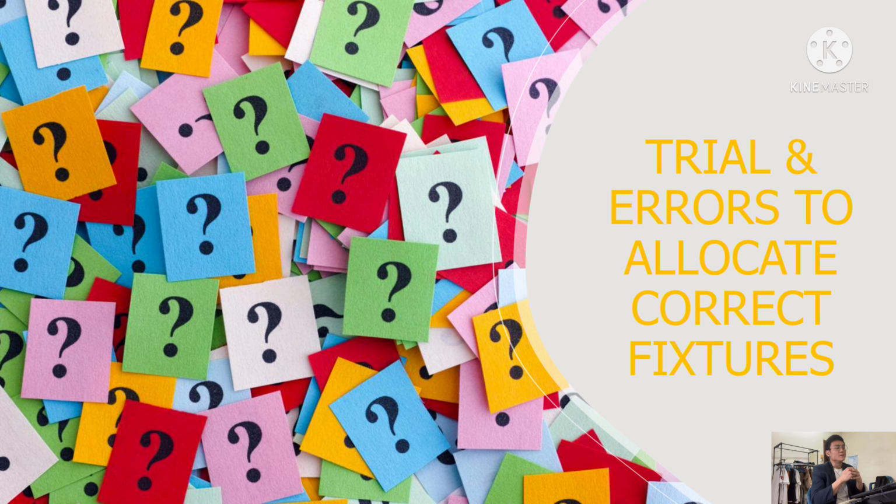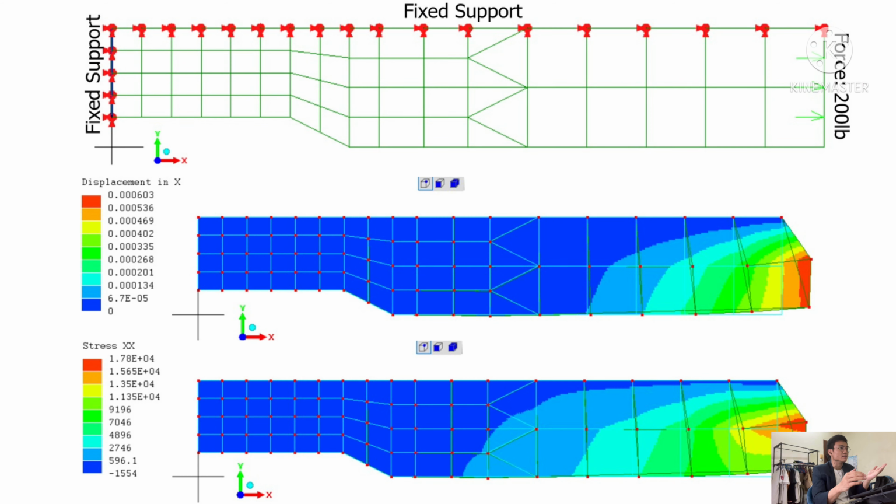So here's the problem. We are not sure about where to apply the fixture and which fixture we should apply. So let's try with some trial and error. In the first trial, we apply 2 fixed supports, one at the left end of the model and another one on the top of the model, while on the right end we apply a force of 200 lb. But it's quite disappointing because the stress seems not to be concentrating at the region that we want.